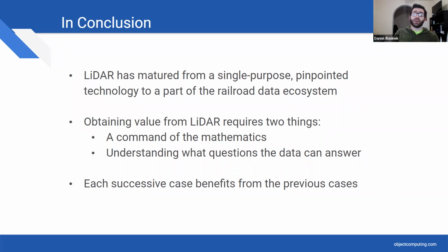And there is one source of public data that you might find interesting, though. It's called 3DEP, all capitals. It's collected by the USGS. They pretty much collected high density terrestrial LIDAR for the whole United States. There isn't very good frequency, though. For example, we were trying to use some to check the accuracy of some of our data, and the only one we could find was 6 years old. So the frequency isn't great, but you can locate crossings in that data. They have the entire continental United States covered.